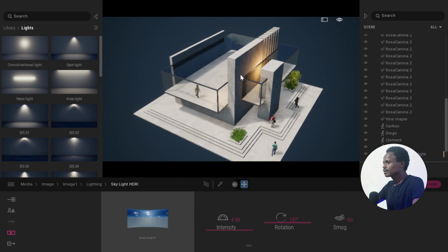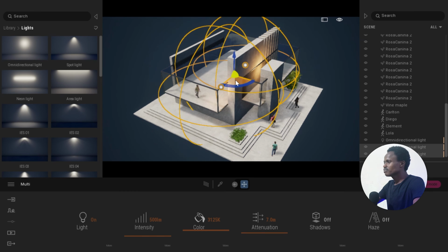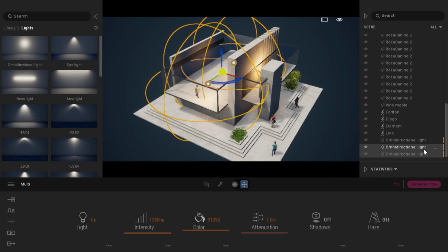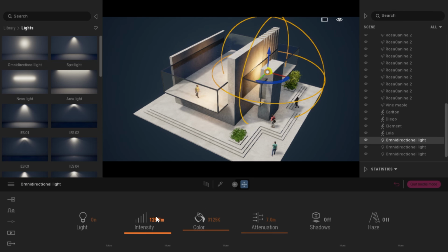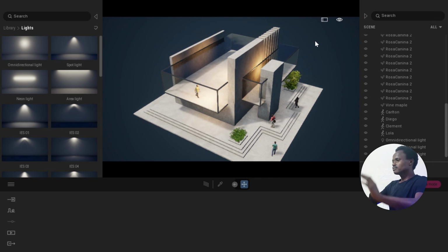Yeah, I do like how the forms form those shadows right there, and we can't seem to see the lighting on the inside of the second, so I'm going to reposition them by sending them within, and perhaps the intensity is not big enough. Maybe we may need to break instance such that we affect this differently. This should be 500, and these can be a little bigger, so much bigger, because they are in a bigger space. Okay, there you are. So we already have something interesting.